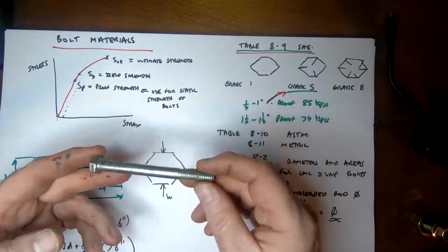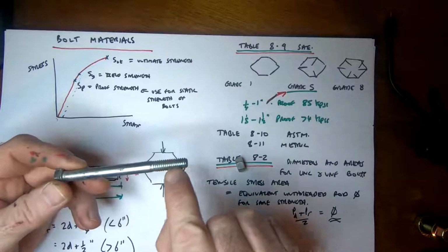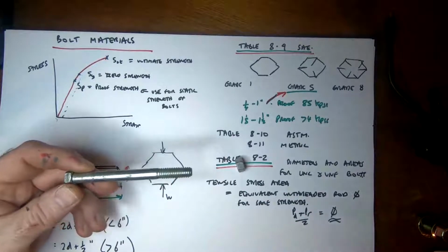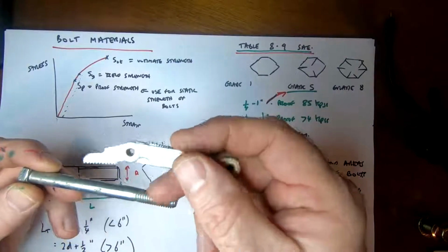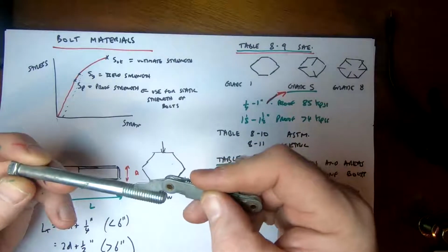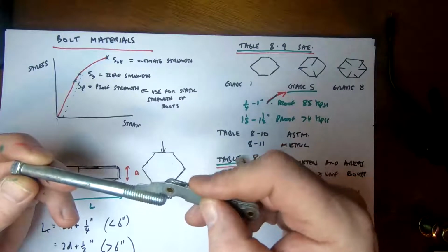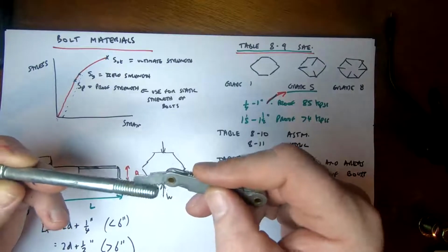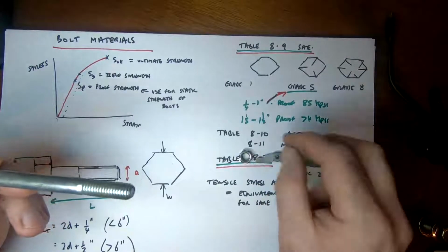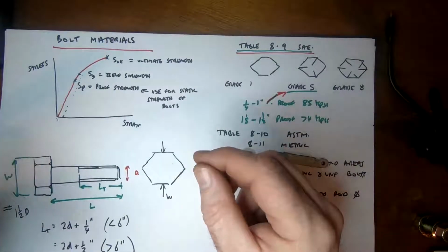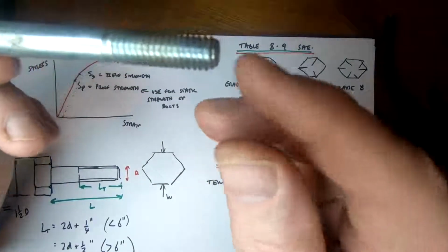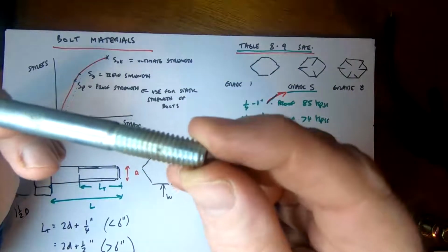So that's an American standard UNC bolt. It's got threads on here. I've got a thread counter. This tool here lets me measure the threads, and that gives me 16. So 16 threads per inch is the actual specification, and that's correct for this one. That's a UNC bolt, and so you can get an idea of the threads on that one.